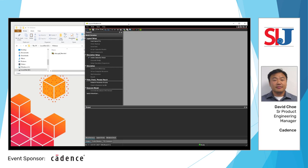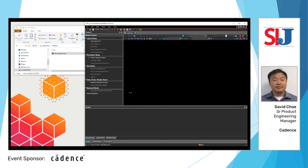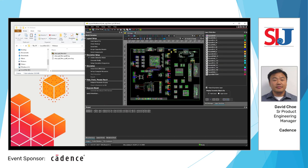So here we see the new interface that is Sigrity X. The GUI has all been changed. It's all been updated. Notice that we are in the black theme or the dark theme. To start off, you can take this BRD file and directly translate it into this interface just by dragging it and dropping it into this window. Quickly translates it, and I'll show you just the few steps that are necessary to get from layout all the